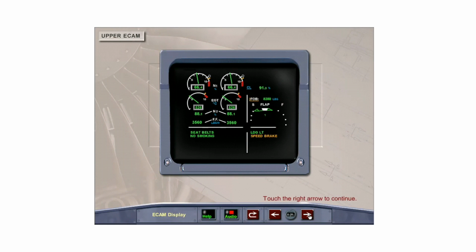Some memos are amber in abnormal or undesirable situations, for example, when the speed brakes are extended and engine thrust is greater than 50% N1. Warning and caution messages, when generated by the flight warning computers, are also displayed on the lower section.